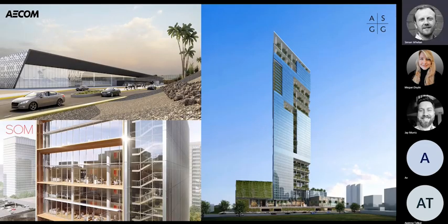So I suppose a number of years ago, when we were in practice, we very much felt that there was a requirement for a tool that could give designers an understanding of these implications of their design decisions of the facade. So things like window to wall ratio, where our glazing is situated in terms of orientation, shading, how is that going to affect things? The spec of the glass, how is that going to affect things? But all of these things are the energy performance of your building.